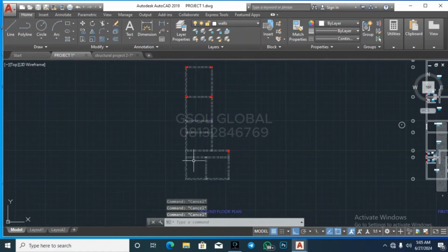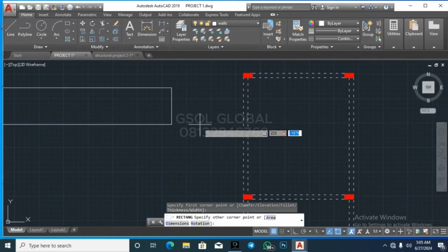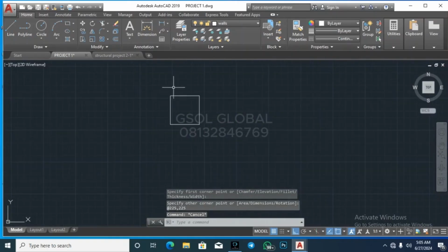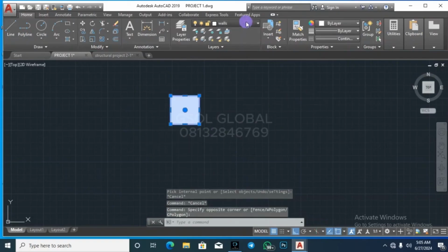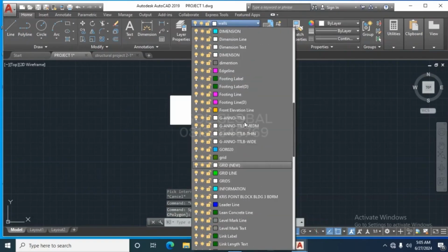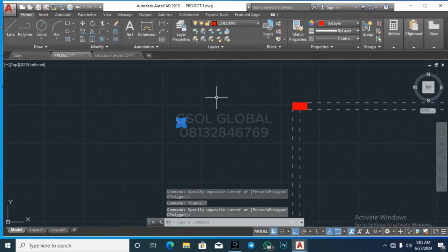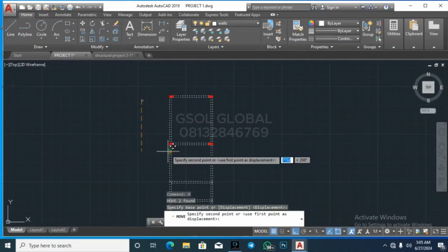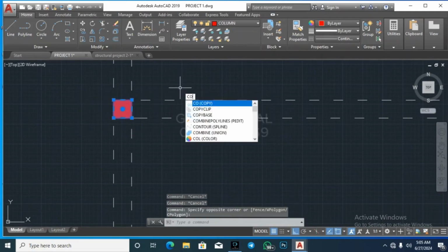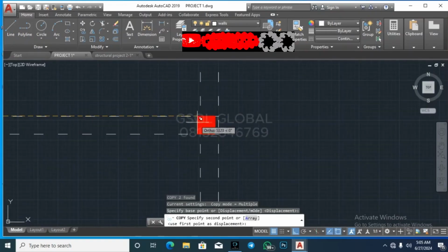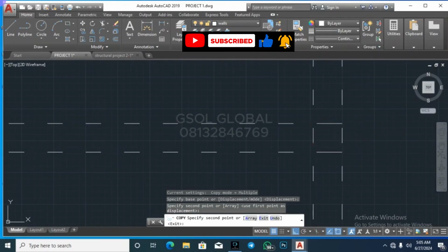So let's go ahead and draw our normal column, that's 225 by 225. All right, so I'm going to hatch inside here, and then I'll convert it to the column layer. So we have this here. I'm just going to move this to one of the spots, and then from there we copy and place. I'll just place it at where two walls meet. That's the safest place to place at first, before you start doing other stuff.